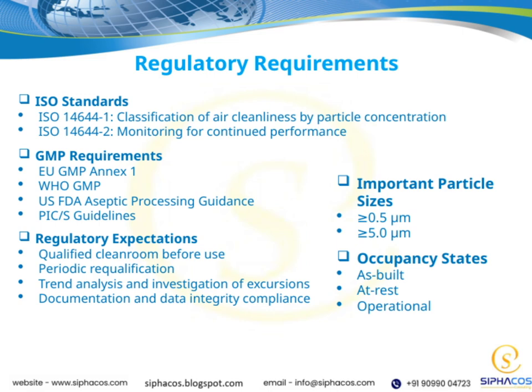Next, let's consider occupancy states, which refer to the different conditions a cleanroom can be in. The as-built state is when the cleanroom is first constructed. At rest means it's not in use but ready, and operational is when the cleanroom is actively being used for production or research activities. Monitoring these states helps us understand how contamination levels can change.